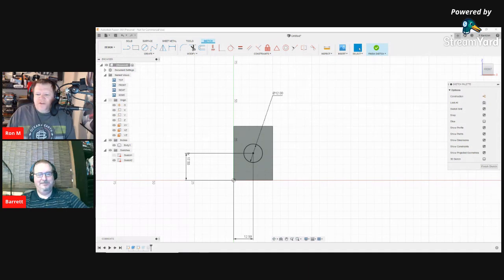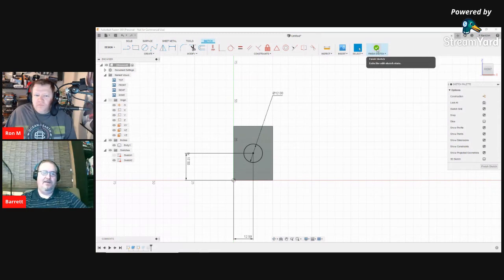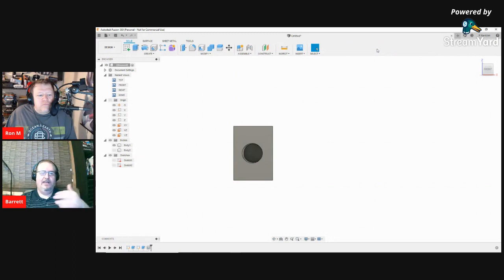So how do you save a design? Say if I wanted to save this right now, I want to go back to it later. First off, I would recommend finishing the sketch before you do that. So just a finish sketch, up here, finish sketch. I don't know that you have to do this. This is just, for me, good practice. I don't want to be in a dialogue, in a function, in a sketch, modifying something at the point that I save. Now, one thing about Fusion 360 is it's auto-saving in the background, but right now you're untitled.